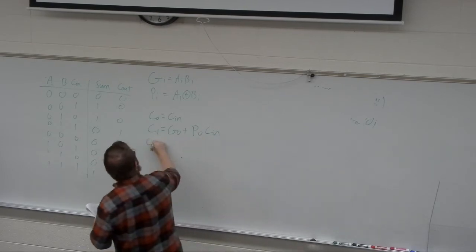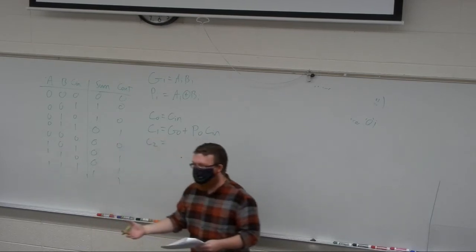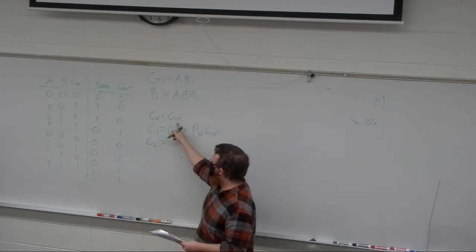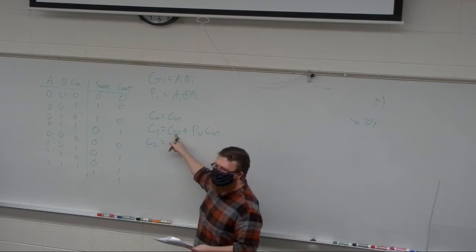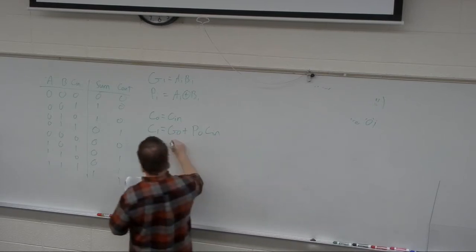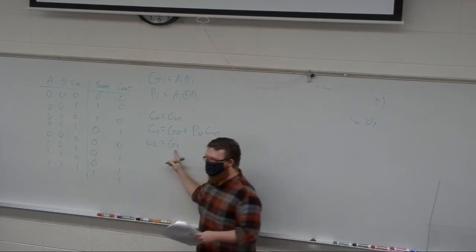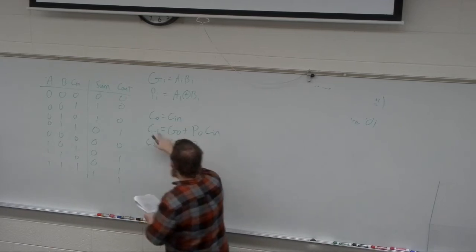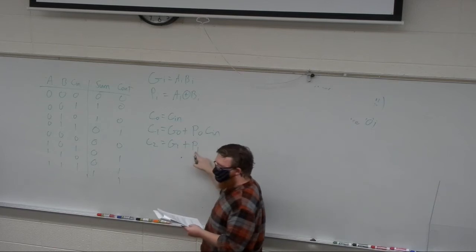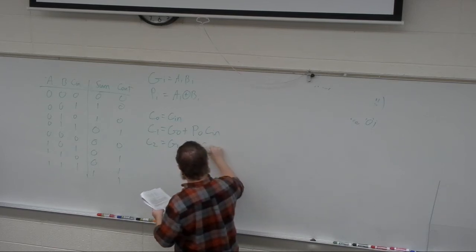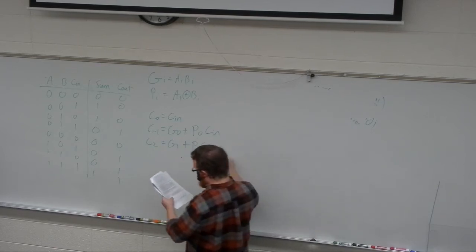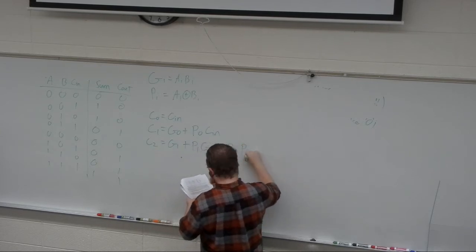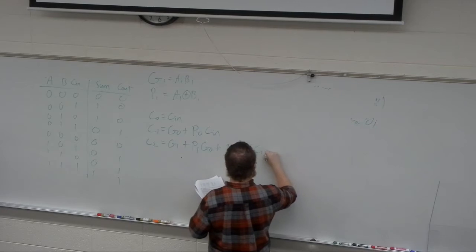On to the next one. Well, now it's getting more complicated, right? Because now I could carry in, generate or propagate, or, well, again, this guy can generate it, or number one could propagate it and generate, or you could propagate one, propagate zero with a carry in.